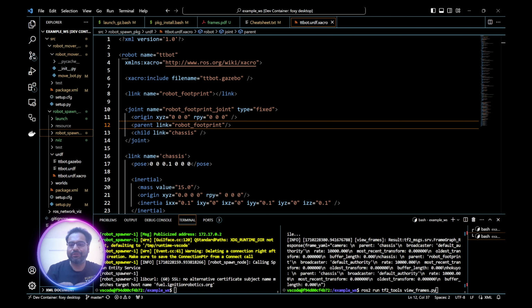It could be a cylinder or a cube surrounding the joint that represents a collision bounding box around it. There are some Gazebo related properties that would be encapsulated inside a Gazebo tag, and there are some material properties that you use to explain the appearance of the robot, so some different colors and so on. Then of course there are sensors and actuators that we're going to go through in just a second. So let's start going over our URDF file and see what is where.